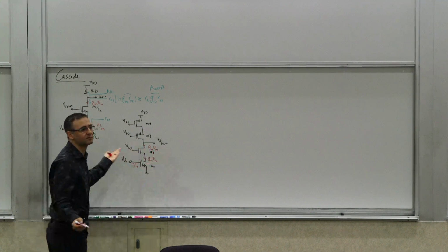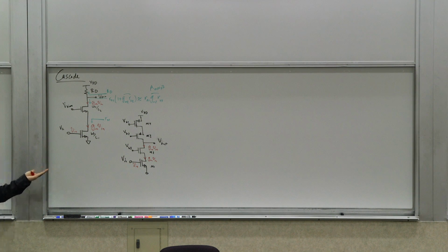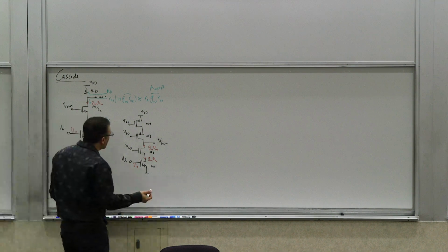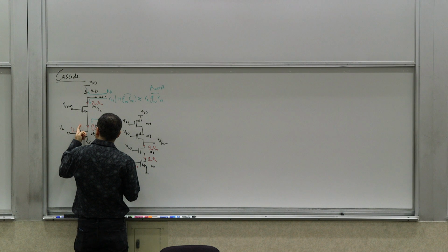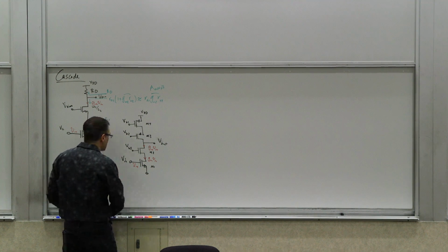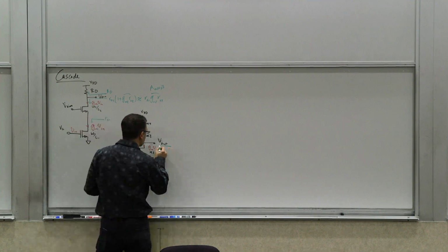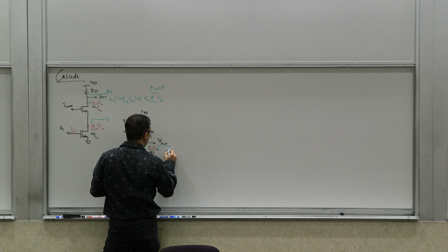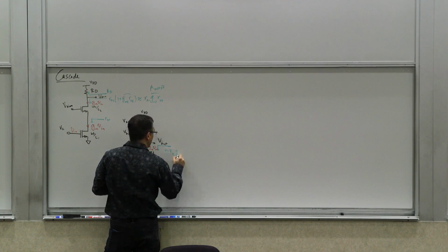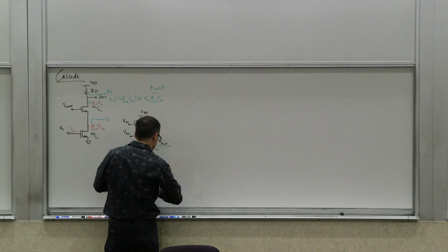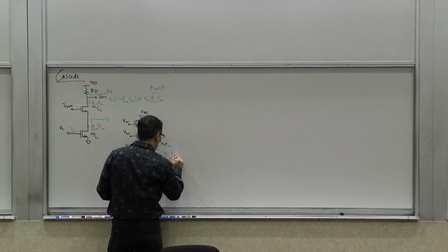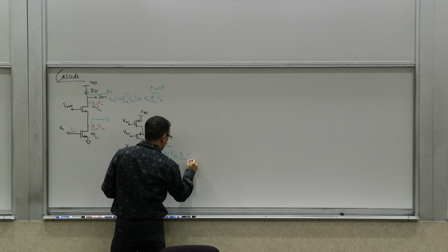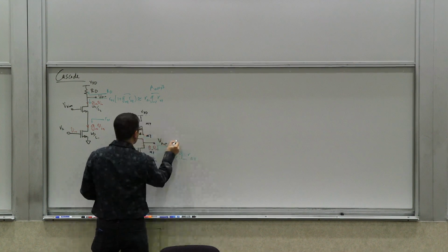So if you had a BJT, it would get multiplied by alpha. The output resistance looking down is still the same thing, so we can write it roughly as RO1 GM2 RO2. And then the question is, what is the resistance looking up?